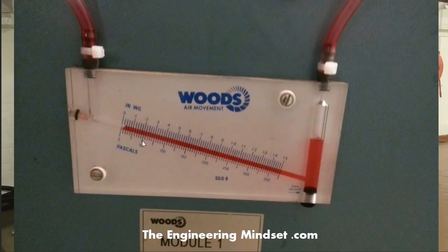A really good tip is to mark these, so put a sticker or draw a pen mark to display where a clean filter reading should be and where a dirty filter reading should be. That way, when your maintenance team does the walk-arounds, if it was at 150 pascals and it's gone up to 200, the red dye, then you'll know that you should have changed the panel or the filters by now, and then you can get the maintenance regime in place to do that.